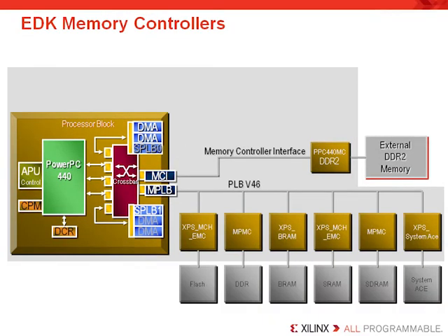Well, this system is a little less typical, shall we say. We really wanted to give you a chance to look at some of the EDK memory controllers and talk a little bit about them. First of all, note that the PowerPC slave peripherals are all connected to the MPLB bus. These memory peripherals, as well as the MCI memory, will also be accessible to other masters that are connected to the slave PLB bus. But in this case, there is no slave PLB bus, so it's again pretty simple. Okay, so again, it's not very typical, but you should note that all of these memory controllers are included with EDK, and I just want to mention a few of these.